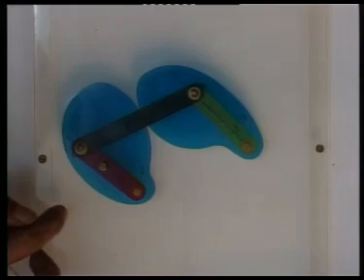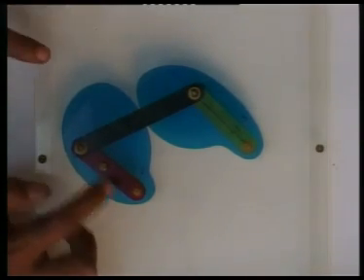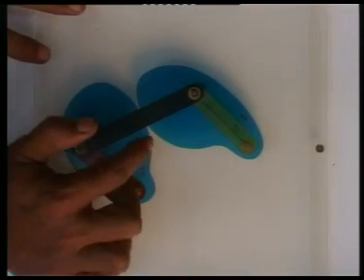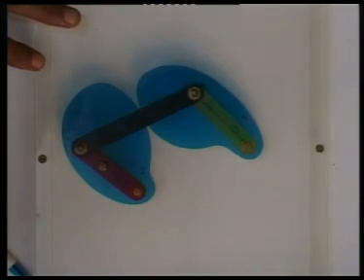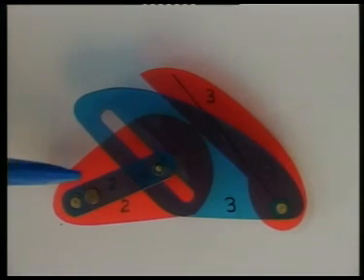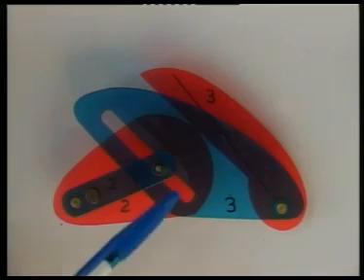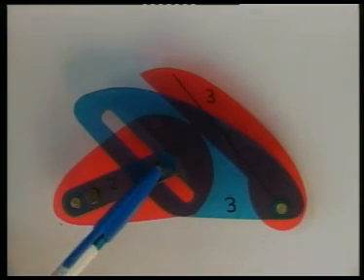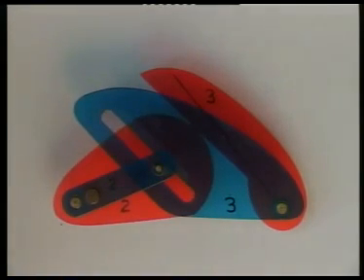We can show another model with one surface flat, that is the radius of curvature is infinity, and the other curvature is a circle, that is radius of curvature is constant. Under such a situation, of course, the equivalence will hold good for the entire cycle of motion. Here is a higher pair mechanism between links 1, 2 and 3, and the center of curvature of body 2 at the contact point is here, whereas body 3 has a flat or straight contacting surface.